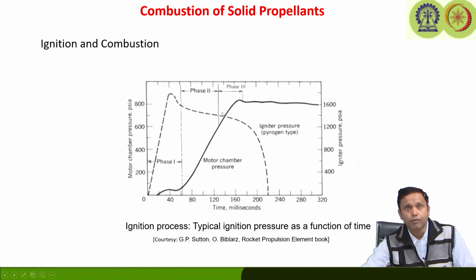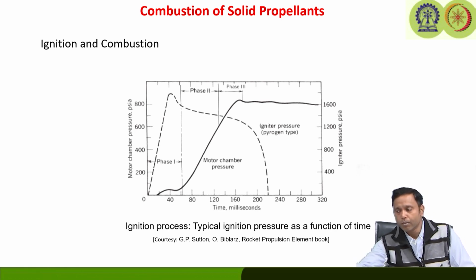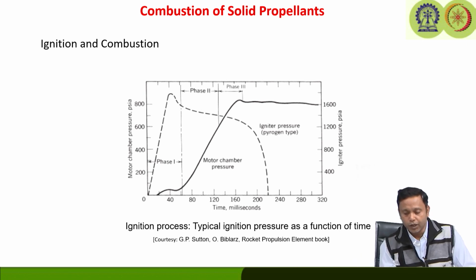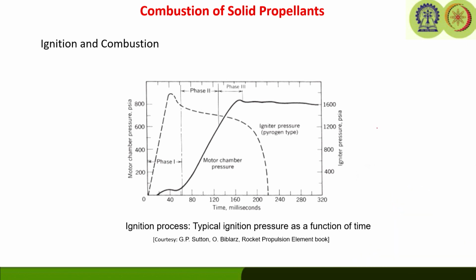That phase is called phase 3, the chamber filling interval. During this duration it will completely fill up the chamber and reach the equilibrium pressure of the rocket, and of course, it will flow. Ultimately, once it reaches that, the products of combustion will flow from the rocket chamber to the nozzle, as you may remember from the configuration we discussed in our previous classes.